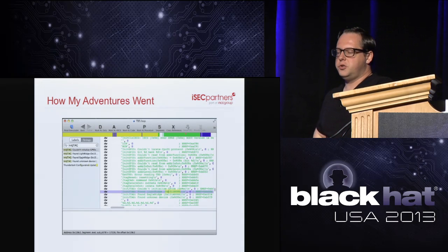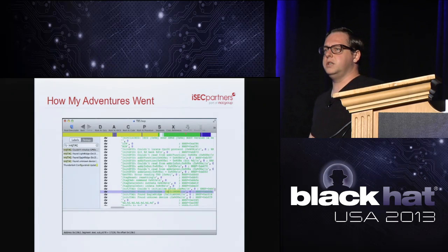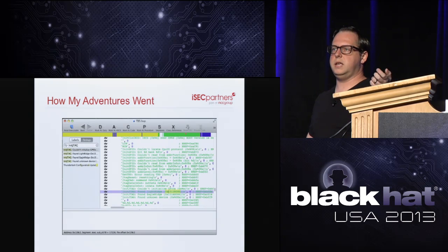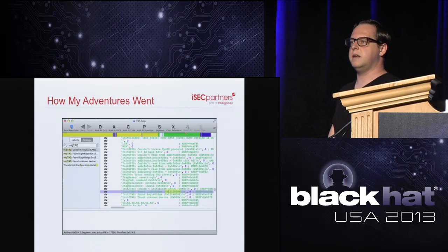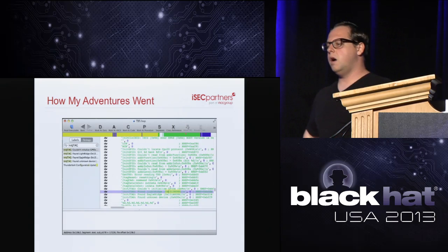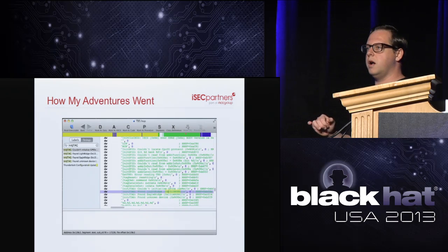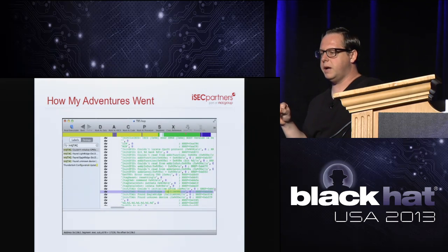Just looking at the strings in the EFI program shows us a lot. We're able to see a lot of debug information, and tracing that out, we can see a lot of functions shown with a colon, like "init JTAG:" and then some issue, or "read EEPROM:". So this debug information is helping us figure out what blocks of code are doing what. Also, we noticed there's a "found Light Ridge" and "found Eagle Ridge", with a 4-byte hex number next to it. That is pretty interesting. I haven't seen anything related to that in any of the Apple stuff. Let's do a little digging around.